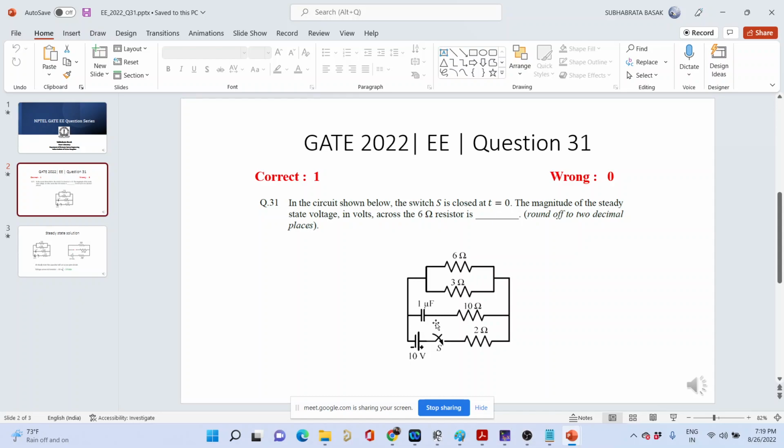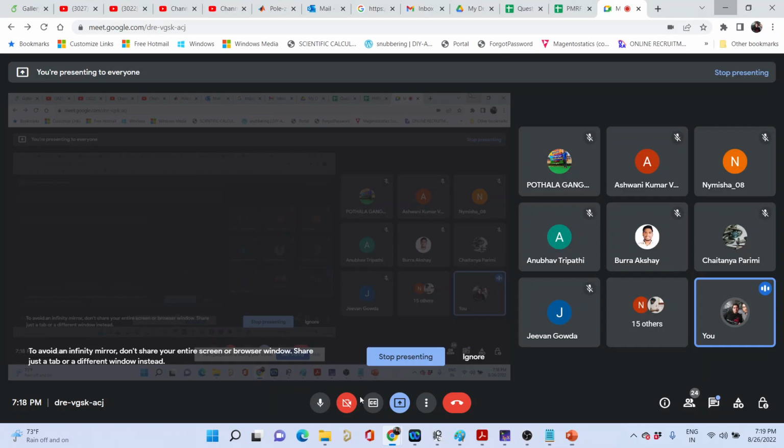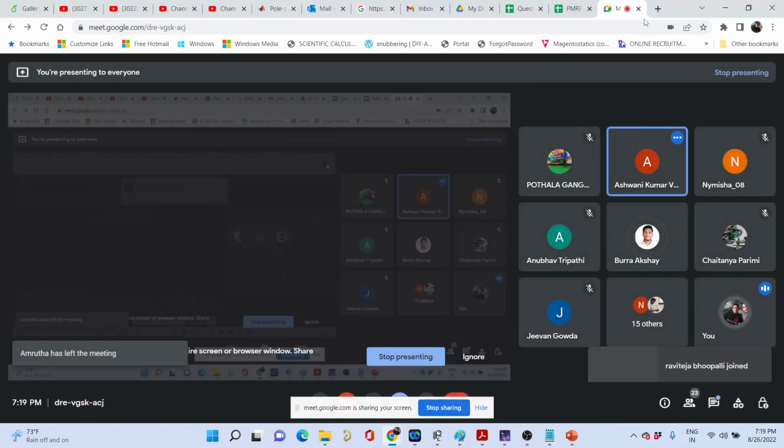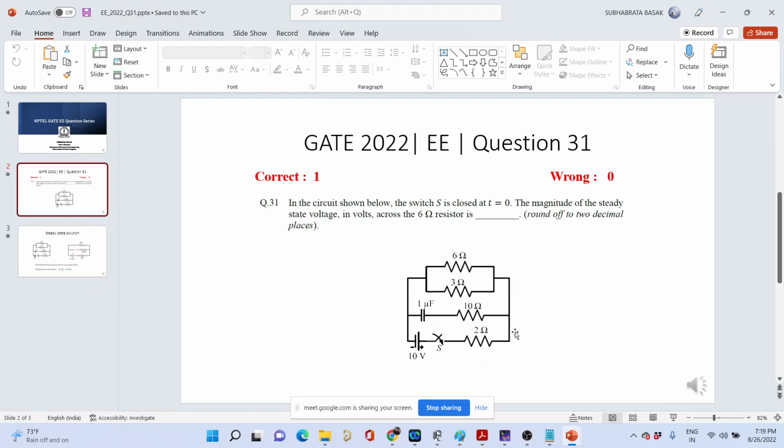What is the voltage across the capacitor at steady state? It should be, sir, 10 volt. At steady state it is 10 volt. Not the final value condition. At final value it is 10 volt. Yes, sir. You are sure? At steady state you are saying there is 5 volt across this, and you are saying no current can flow through this. So how can this be 10 volt? If it is 10 volt, there will be current flowing through it, right? How is it 10 volt?